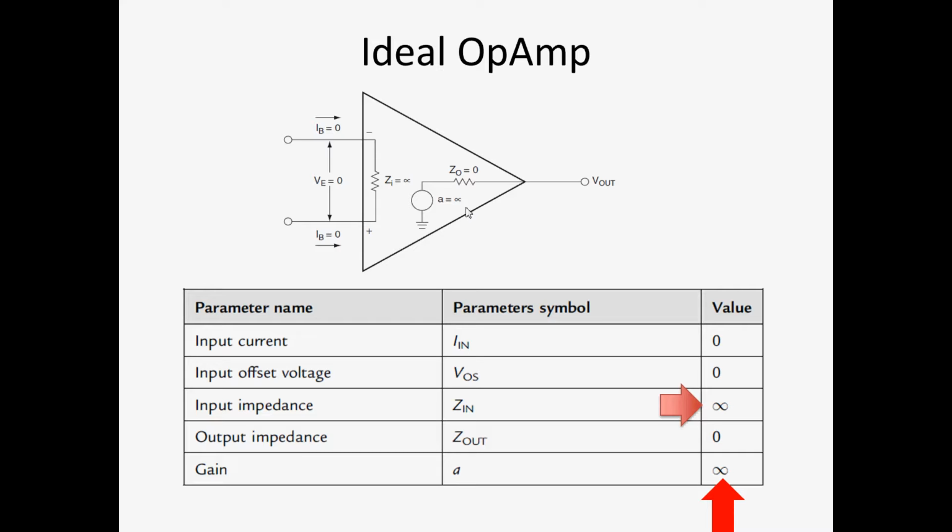This means that the driving capability is limited by the power supply as well. So if your power supply is, say, 10 volt or 9 volt, the typical 9 volt battery, the output of an amplifier cannot exceed 9 volt. Let's make an even number: 10 volt power supply, maximum 10 volt output, and a gain of 10.